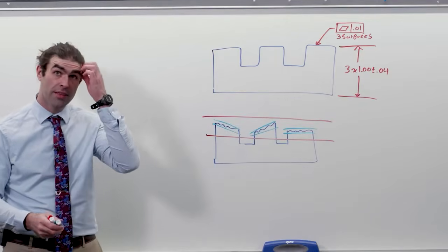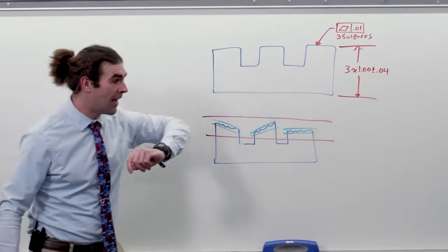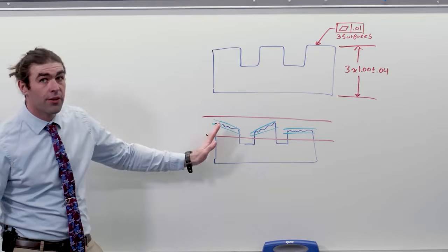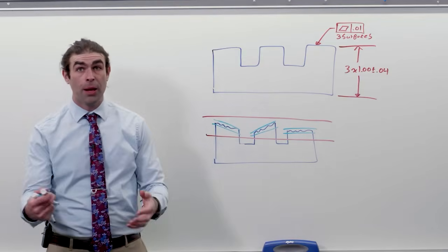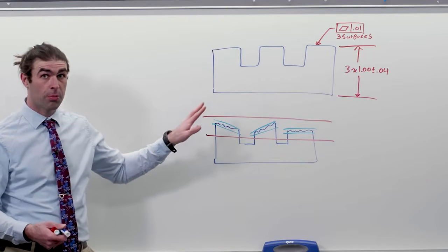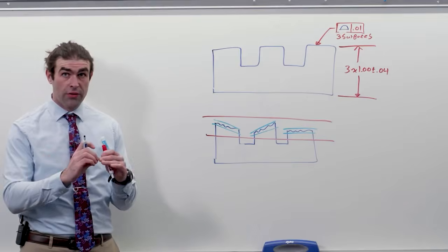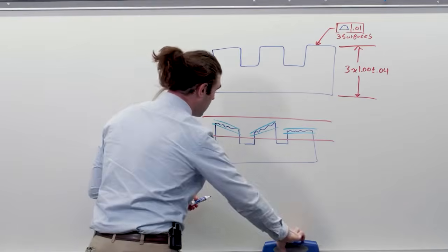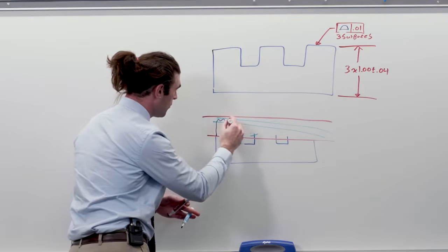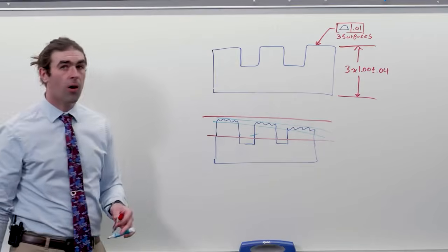So you could end up with something like this, where the 2 red lines are indicating the total tolerance within the limits of size, and the individual blue lines indicate this 10 thousandths of flatness. Each surface is flat to itself. Now, this might be okay in some applications, but it's worth knowing that that's the requirement you're putting on the drawing. Now, what profile does is control the surfaces to each other. So instead of them being individual, now the tolerance zone goes the full length, and every one of these surfaces must fall within that tolerance.